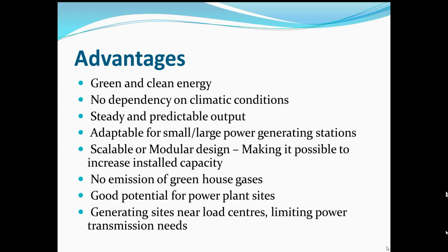Moreover, it is scalable and modular in design. Now, why do we say it is scalable or modular in design? The efficiency of the power plant can go up or down by altering the number of membrane modules. So, suppose there is a need for high power to be generated from the same osmotic power plant, then the number of membrane modules can be increased in order to have a greater head. In a similar fashion, if we need a lesser capacity, then the number of membrane modules can be reduced.